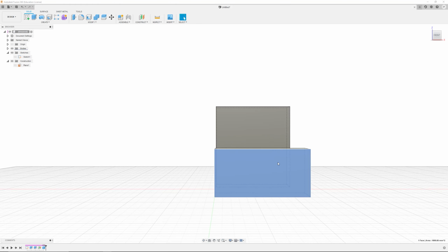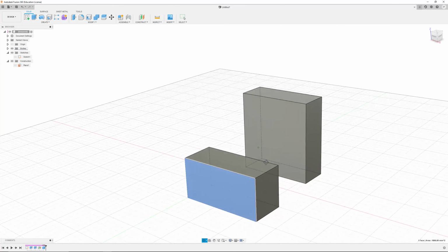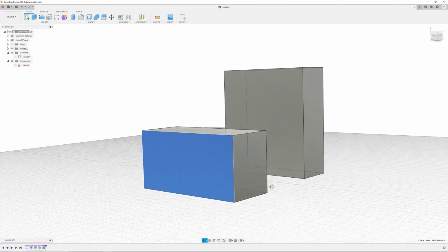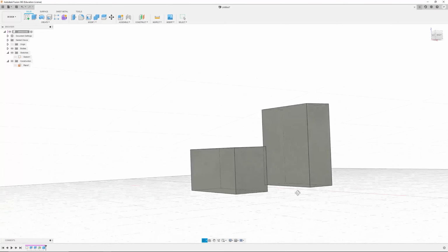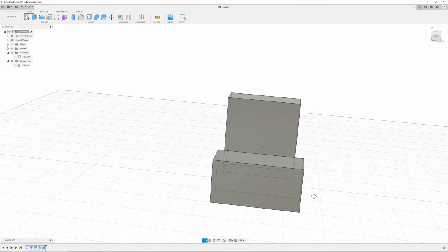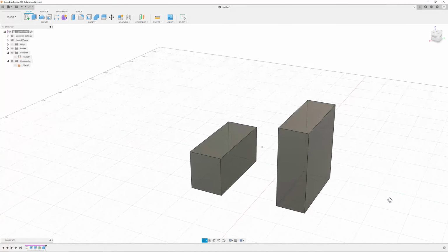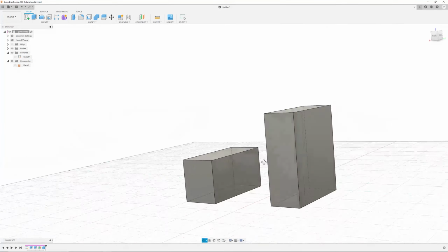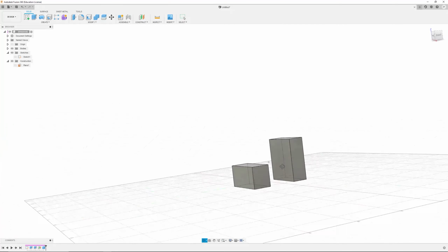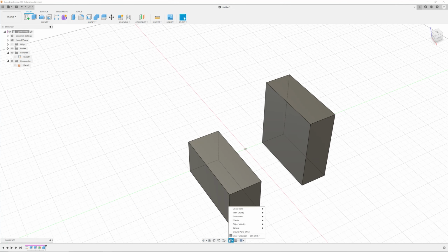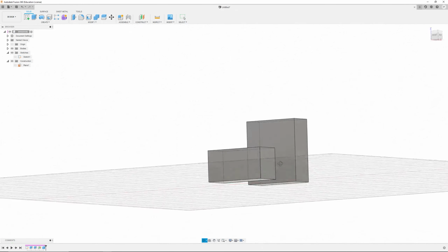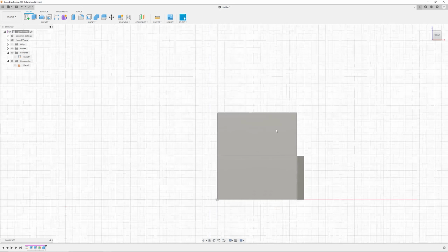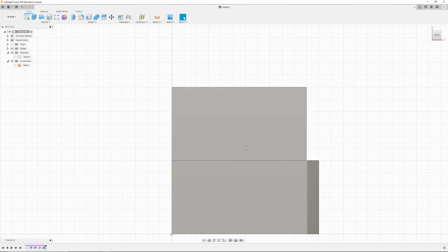This is what the difference is between perspective and orthographic if you didn't understand it from before. These do look more realistic in terms of how we perceive things in reality. And this is a good thing to do for renders. So when you render stuff, rendering in perspective is always preferred. But when you're modeling, perspective is not helpful whatsoever. So you want to make sure that your camera is set to orthographic, because that way when I view this, I'm not getting all those extra lines and I'm viewing it as a straight on view.